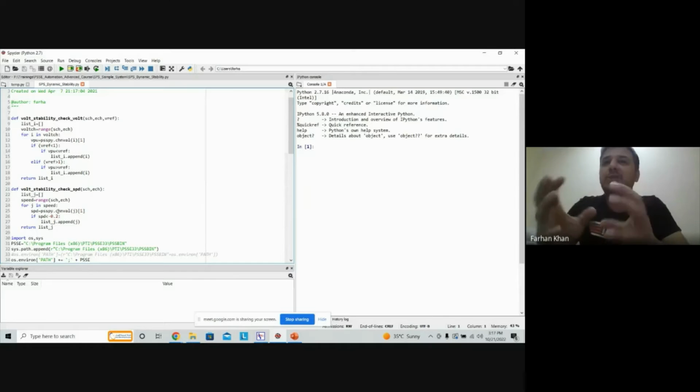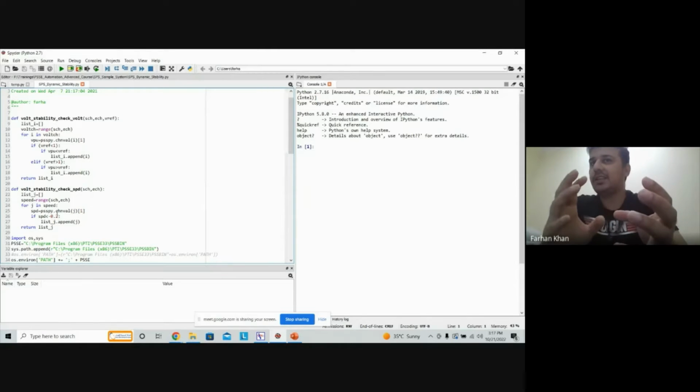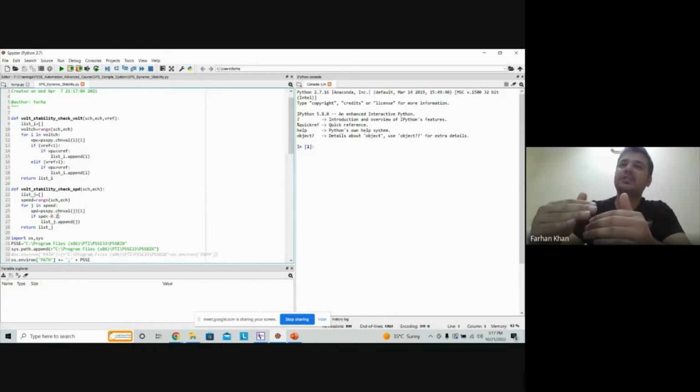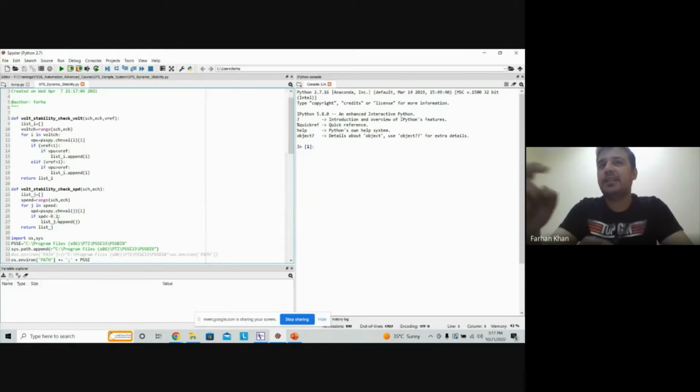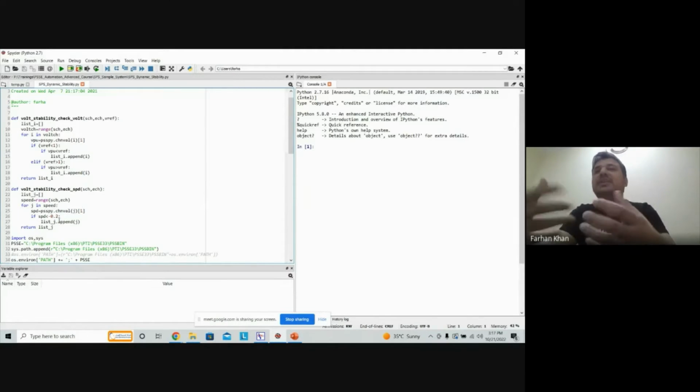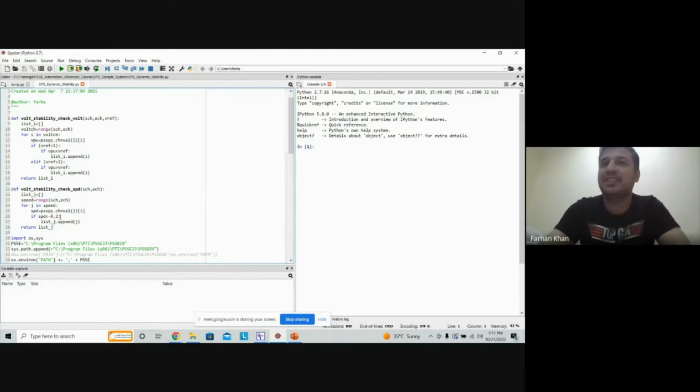This is basically based on how you plan your channels within your snapshot file. What I like to do is make everything in a sequence. It becomes easy for me. Let's say if I want to monitor P electrical, initially I will select all the channels related to P electrical. Then if I want to monitor voltage, all the voltages of all the buses in a sequence. So it becomes easy to handle. This is my way of doing things, but anyways, you can do as you want.